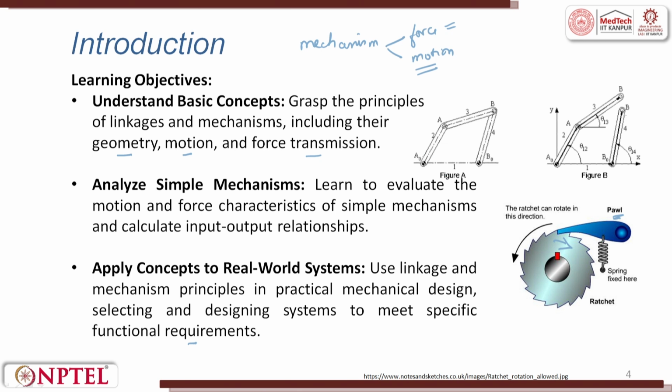And linkages, if you see, have joints and links. When we try to pull one, you can have some motion, like a sector getting cleaned, a wiper which is getting moved. This is a closed one, this is an open one. Interestingly, in the link you have to define the length, and when you make a joint, you will have to define a theta there. So, this is theta. What angle does the link move with respect to the joint?